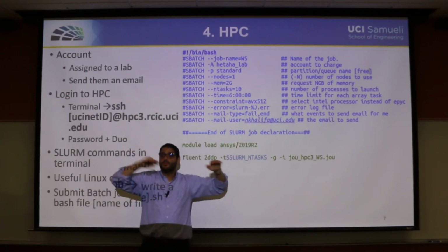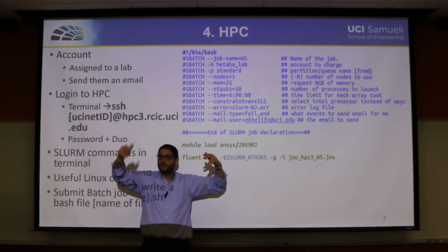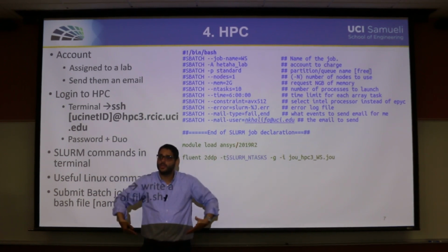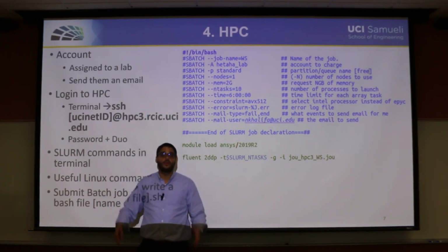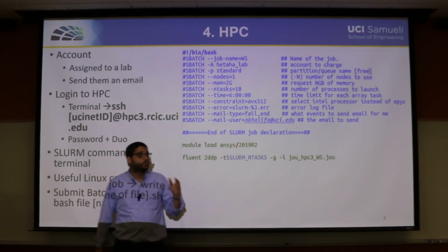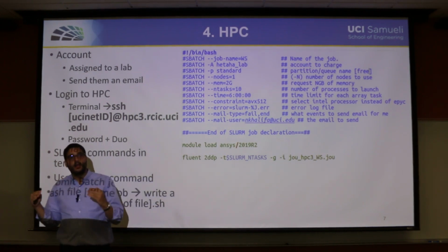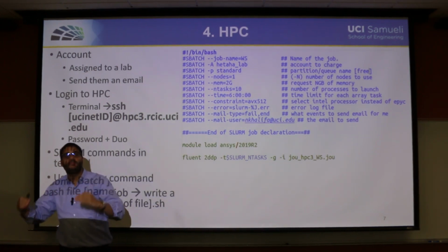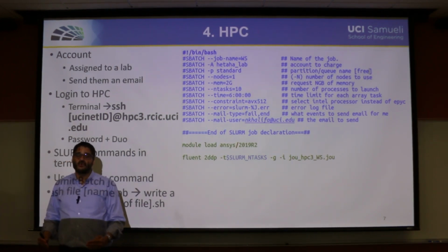These processors communicate with each other through a very fast network that's much faster than the clock speed of the processor, so as not to slow that communication process. And you get to execute your problem or your Fluent software on 3 different nodes, not on one node. To be able to do that, Fluent must be notified before opening its parallel environment that, hey, you will be working with a Slurm scheduler, and that Slurm scheduler is assigning you 3 different nodes, and these are their names.